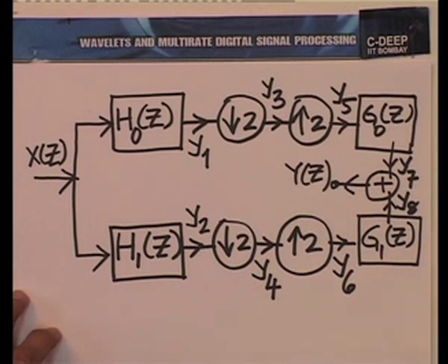So, this is a strategy which we might find useful in some circumstances in analyzing multirate systems, particularly when you have a downsampler followed by an upsampler. If you have a downsampler followed by an upsampler of the same factor, it is sometimes easier to go past both of them and then jump back behind the upsampler. We will do exactly that here.